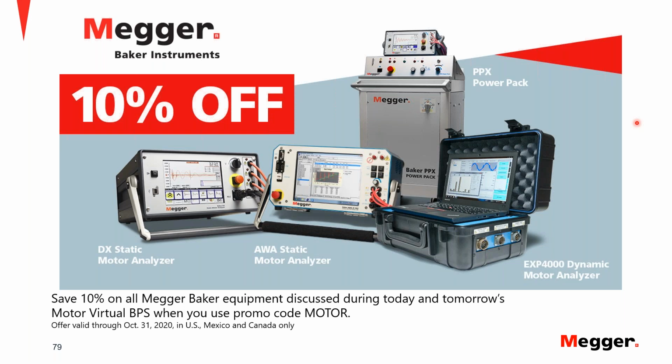So every 360 electrical degrees of that motion, you will have a sinusoidal movement of the magnitude of the inductance. It never goes to 0, but it does have a maximum and a minimum, and it has an average value around which it moves, right? So the point is that if you do that for phase A, then for phases B and C, you will most surely have a different value of the inductance.